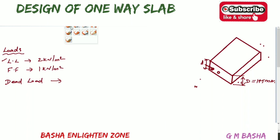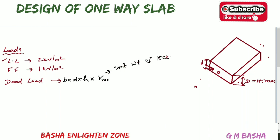Here what I am telling means B into D into H into the unit weight of RCC. So this is the unit weight of RCC, which is given as standard, that is 25 kilonewton per meter cube. So the unit weight of RCC will be 25 kilonewton per meter cube.